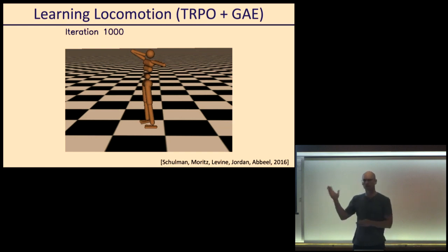And this is actually much more flexible, because if you think about it carefully, the neural network processes the state, and it doesn't directly switch from one linear controller to another one where you switch modes. It's a very gradual thing. It's along one axis in a high-dimensional space that you just make one change. And so it's a per dimension, but not axis-aligned dimension, changes to the linear controller, rather than one linear controller to the other one to the other one. Very gradual changes in comparison to typical hybrid control systems.